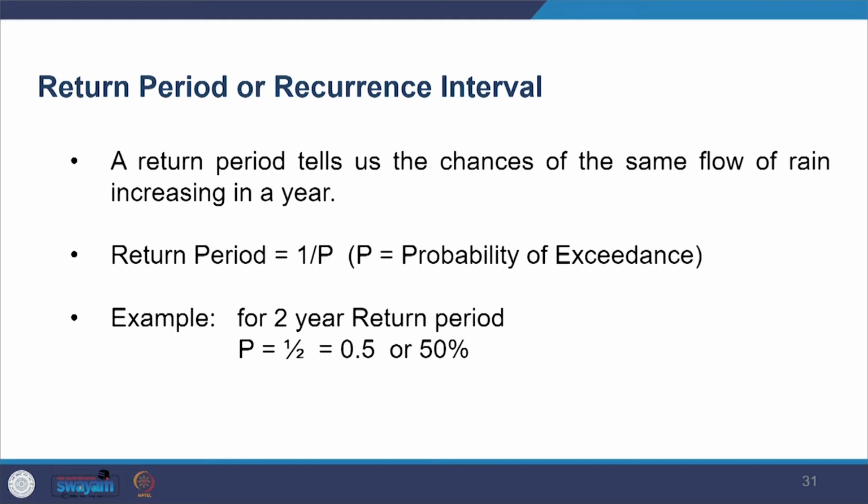We see that the 100-year event is usually used for flood risk mapping. For environmental assessment purposes, the proponents have to establish that the development they are proposing will not increase the likelihood of a particular return period event, and therefore will not increase flood risk to the properties downstream. The return period flows can also be used for the purpose of channel designs and in low flow assessments.